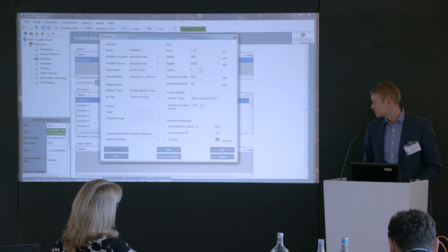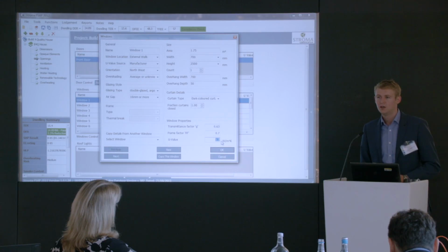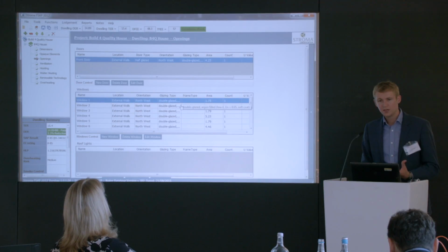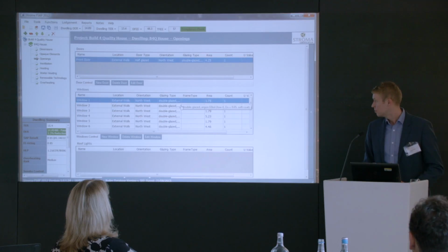And then obviously the U value, so how much heat are we actually going to lose from this window? The U value here is 1.3 at the moment. The notional value used to work out the target is 1.4. I think it's probably safe to say you could get down to 1.3 on double glazing systems. If you start going much lower than that, I think you're probably moving into triple glazing, which obviously increases the cost somewhat. So I have to model all of our windows, taking into account the orientation, glazing area, and G value.